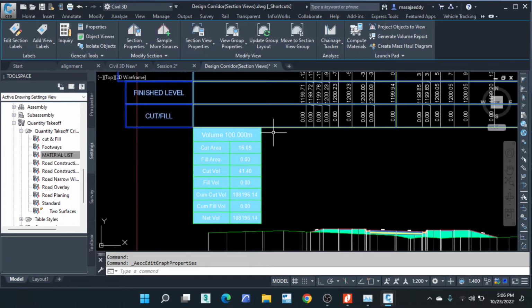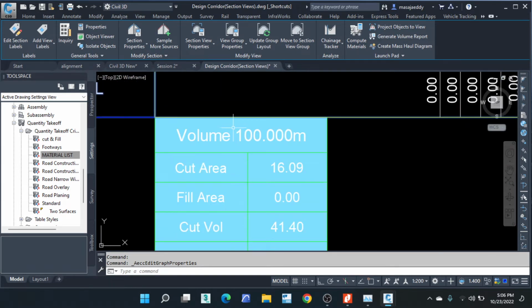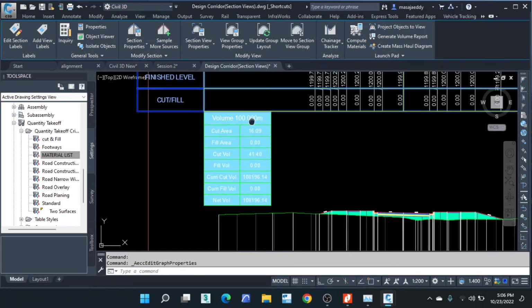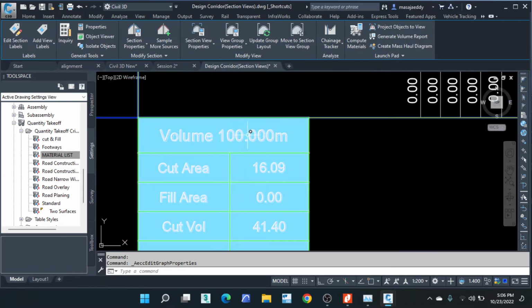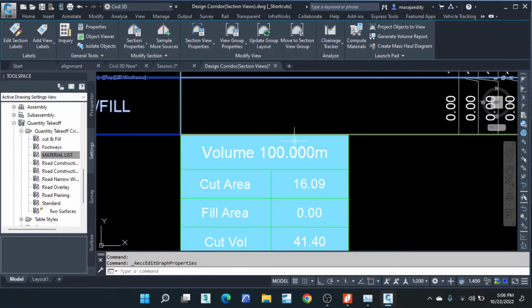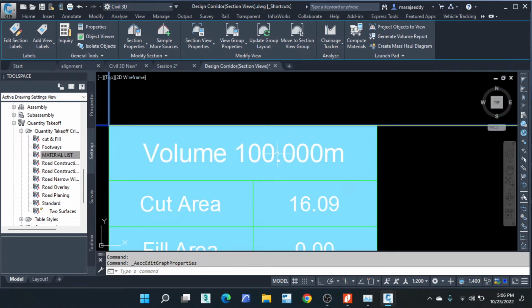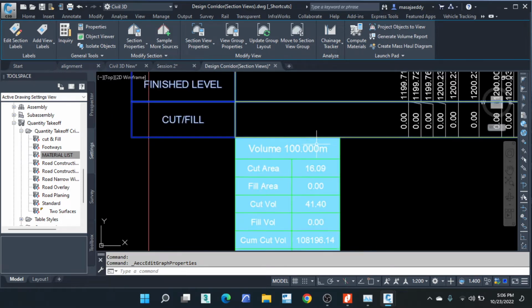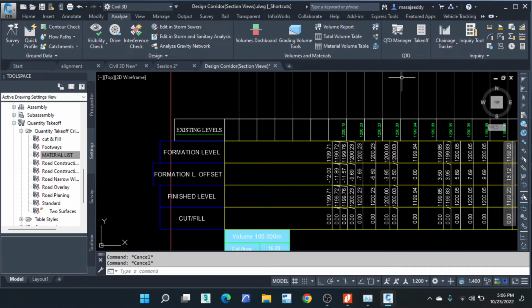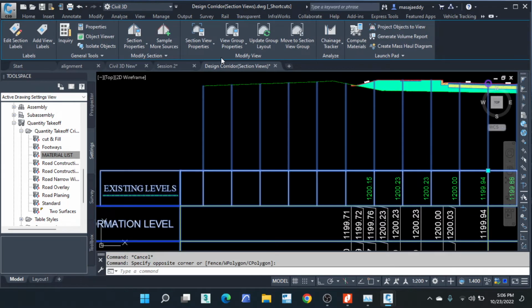You have volumes for cut and fill area, as you can see. You can edit the table. I can't go really through the styles and labels for the table, but here is supposed to be a change value. Unfortunately, for the UK kids, it orients these variables in terms of 100, which is not a chainage format. It's just a decimal format. If you remember last time at the beginning, I explained something like this. So you can just change the format to a chainage format, okay? That orientation. So that is just for the cut and fill. We shall later generate some of those reports.